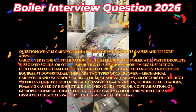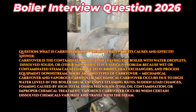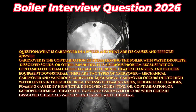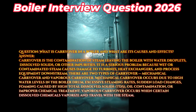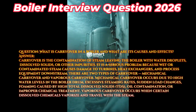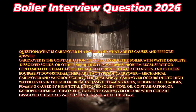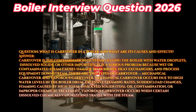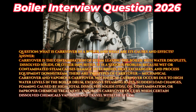There are two types of carryover: mechanical carryover and vaporous carryover. Mechanical carryover occurs due to high water levels in the boiler drum, excessive steaming rates, sudden load changes, foaming caused by high total dissolved solids, TDS, oil contamination, or improper chemical treatment. Vaporous carryover occurs when certain dissolved chemicals vaporize and travel with the steam.